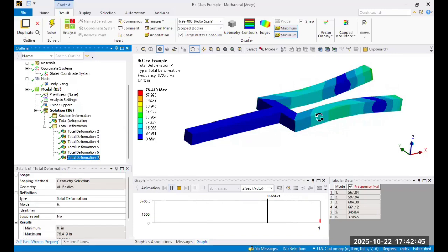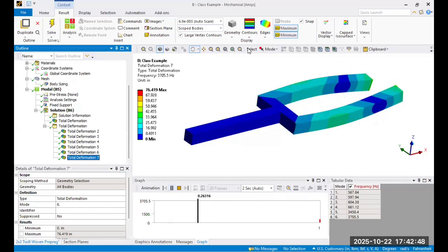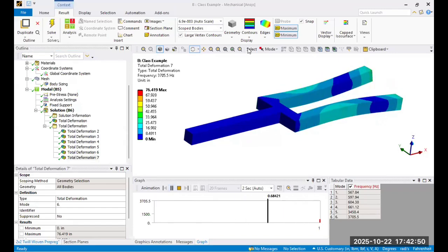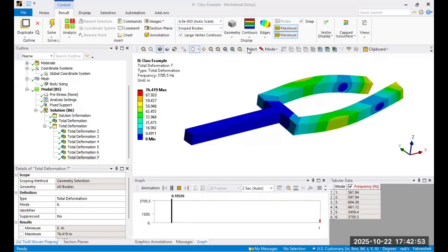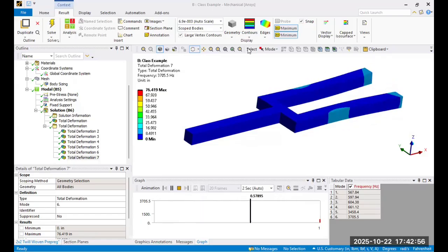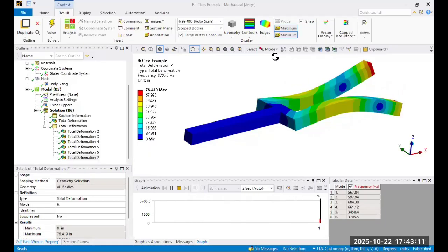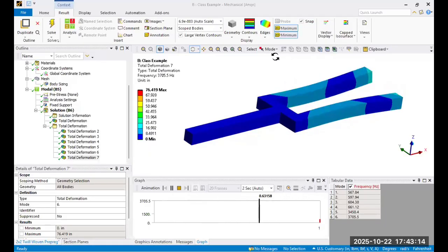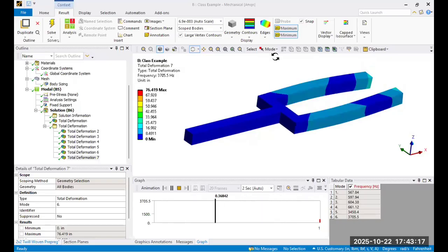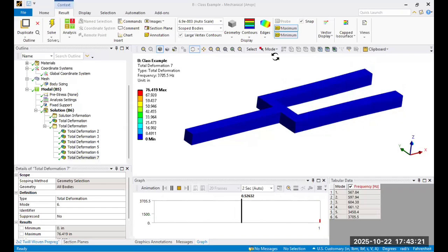Another example is the engine itself, the engine of an aircraft or even a liquid rocket engine. In those two cases, you have the spin motion of the turbine wheel, and that spin has an RPM. So you're going to have frequencies driven by the shaft rotations, and that shaft rotation can potentially interact with the bending modes of each of the blades of the blisk, the turbine wheel. That turbine wheel is like a fan, and each of these blades can bend.